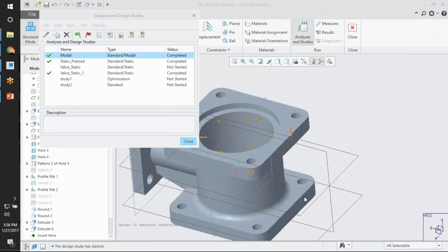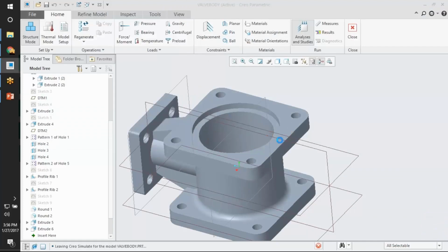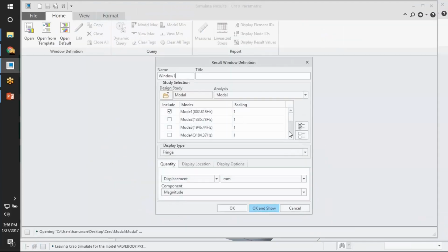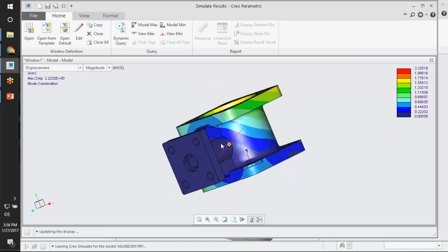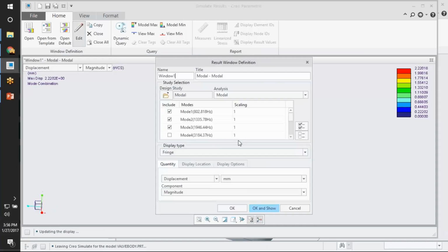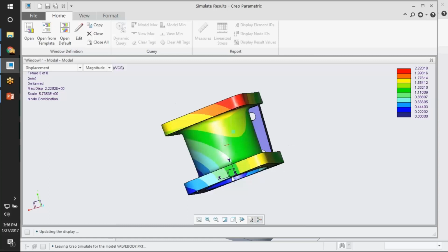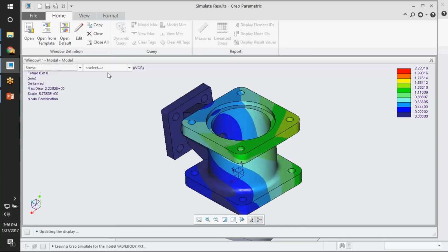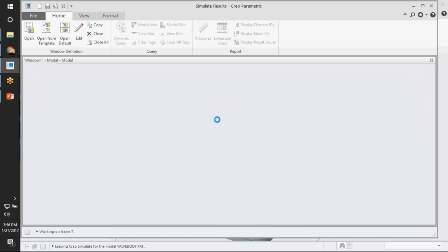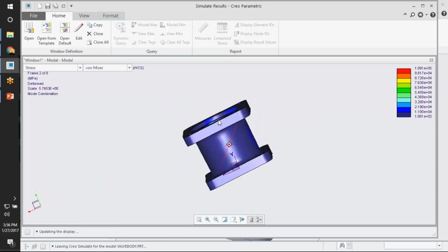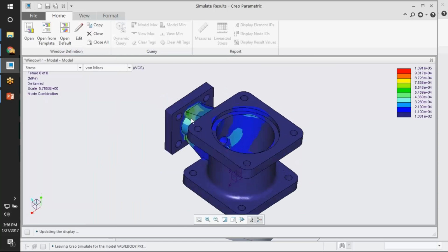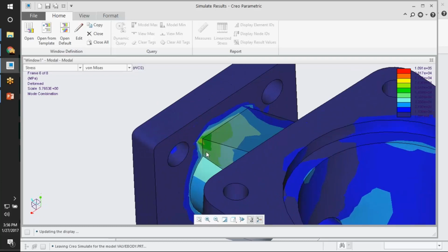So the analysis is completed now. You can see the natural frequencies as mode 1, mode 2, mode 3, mode 4 and different modes, and you can combine the modes. So the typical combination of modes, various mode shape changes and the stresses, all the typical stresses. It's a typical von Mises stress due to this mode, and you can see the stress contours over here.